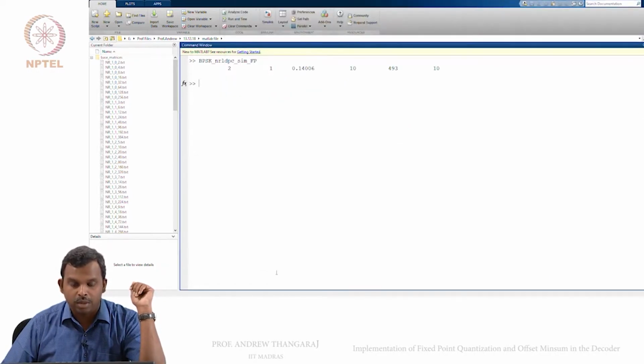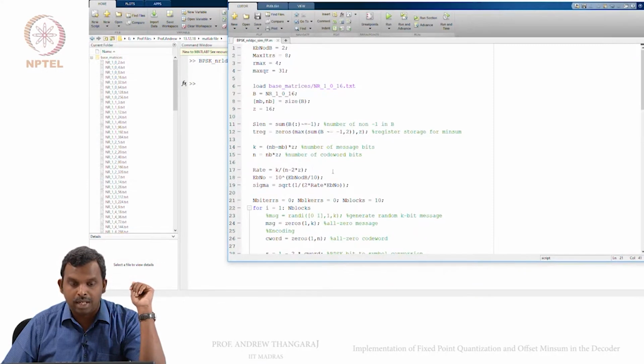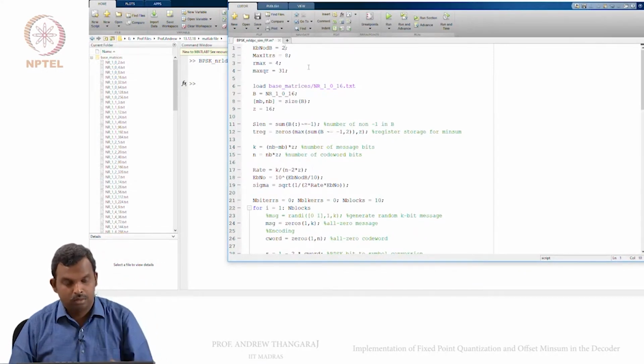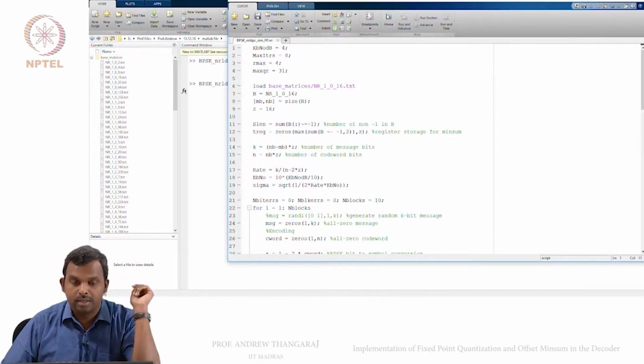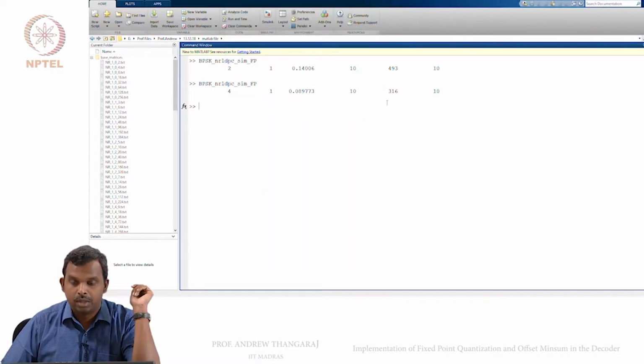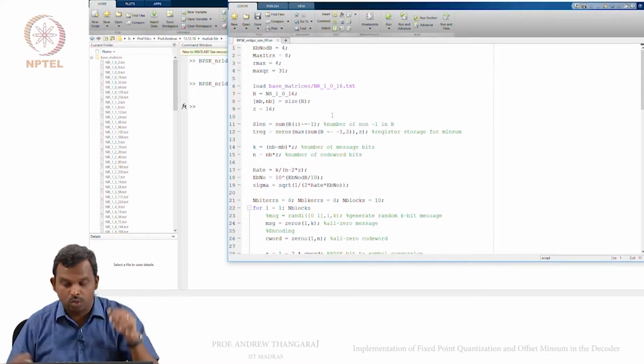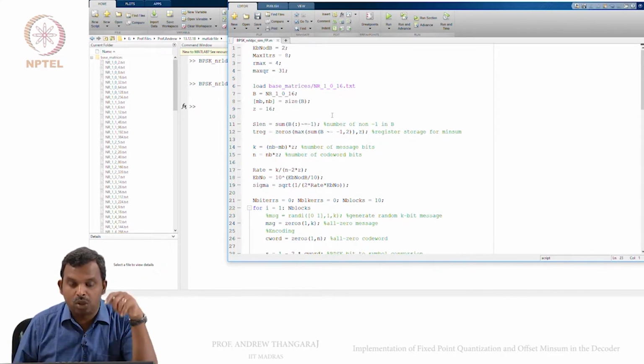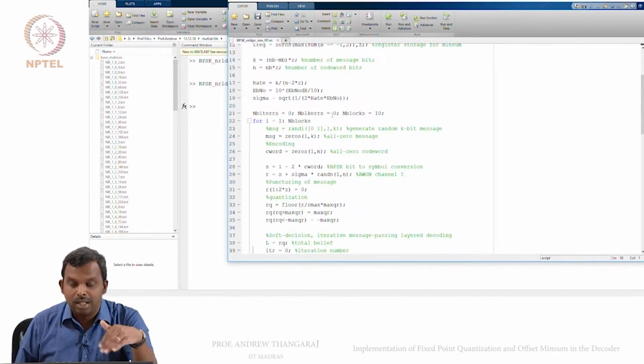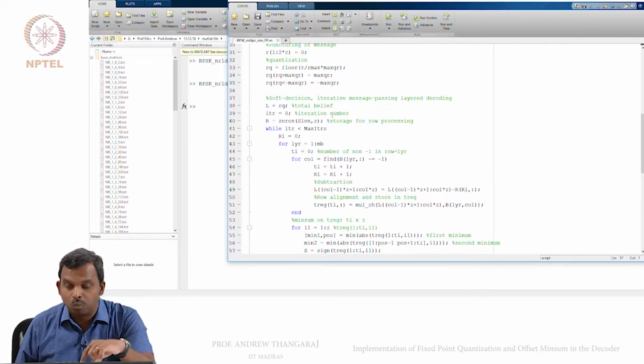Okay. So, you see you are getting some errors, so maybe you can go to a larger SNR. Okay. So, you are getting a lot of errors here. Okay. So, you see even at high SNRs the errors do not go down. Okay. So, the quantization seems to be hurting you in some way, but one needs to also be careful about how we have done the quantization. We just limited it, but then we are not limiting the other values carefully.